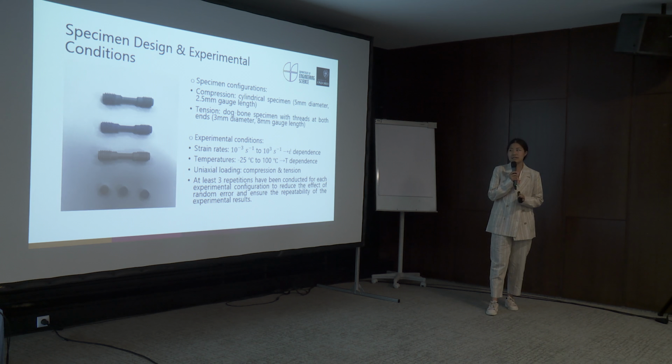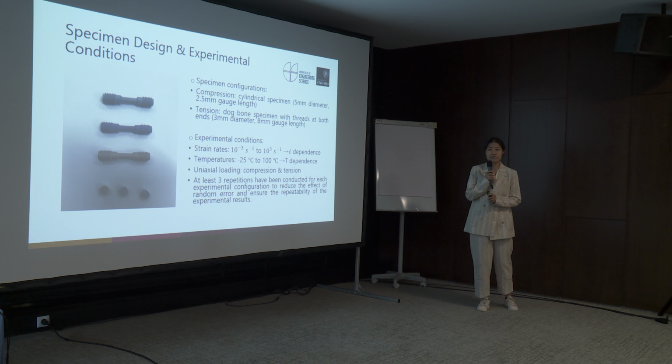We have studied the strain rate dependence, the temperature dependence, and the loading mode dependence of these polymeric syntactic foams. The experiments were conducted at strain rates ranging from 10^-3 per second to 10^3 per second, and at temperatures ranging from -25 degrees to 100 degrees, under compression and tension loadings, respectively.